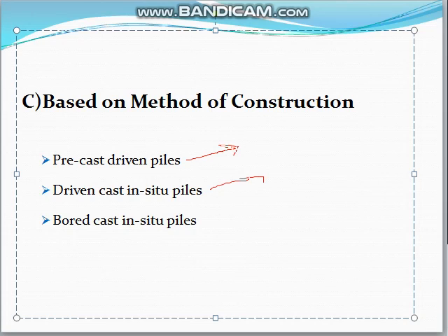Okay. So here, driven cast in situ piles. These piles are formed by driving a tube with a closed end into the soil strata and then filling the tube with freshly prepared concrete.